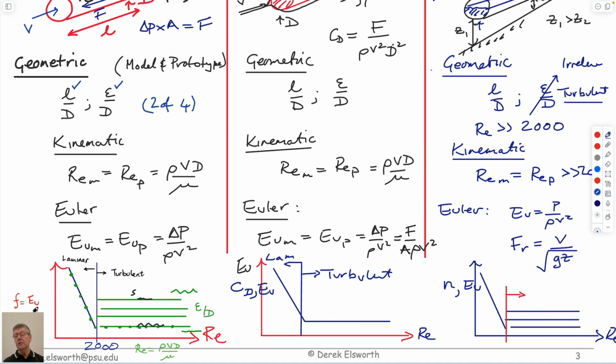So what that allows us to do is you could now do an experiment where you have a tube and you run flow along that experiment and you run it at different Reynolds numbers. So you run it at 1 meter a second, 2 meters a second, 3 meters a second, 4 meters a second with the same fluid in it. And at those 4 different Reynolds numbers, you plot the pressure drop between upstream and downstream that you measure. And so you end up with 4 or 5 different points that give you a curve. And you plot that curve.